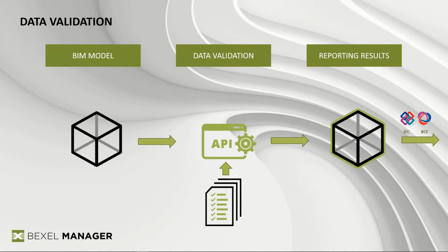So the basic principle behind data validation module in BEXEL Manager is actually that user can establish the rules or the data sets that should be populated in the model in the form of Excel spreadsheet, open this rules or this checklist in an add-in or API engine, and the user will get the series of selection sets with all the elements that just don't comply with the said rules.